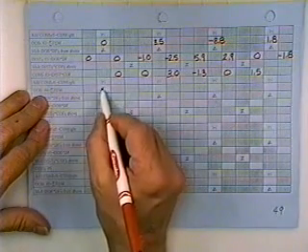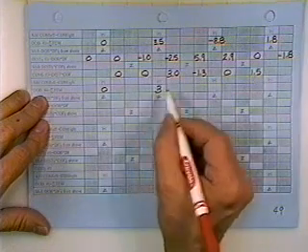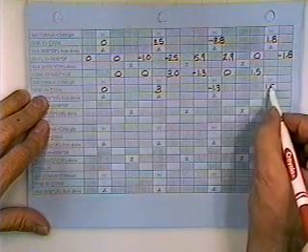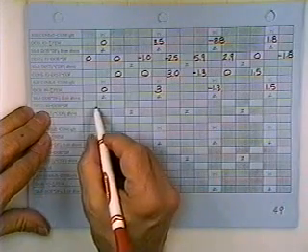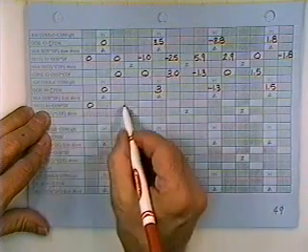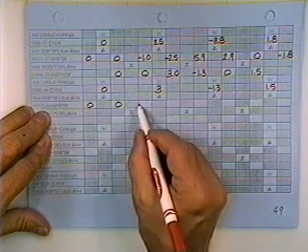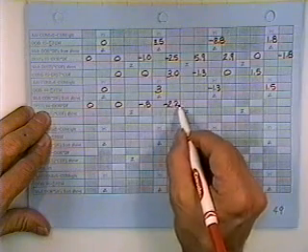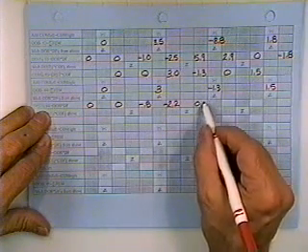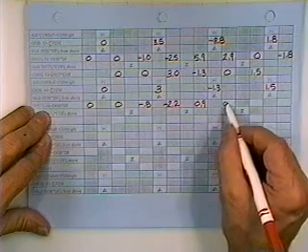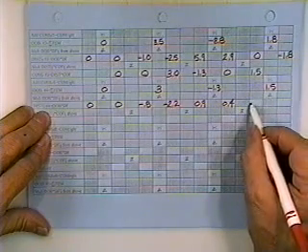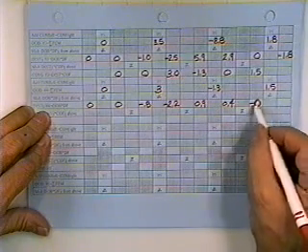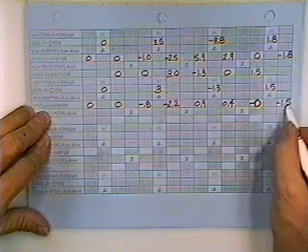Give them to me. Out of balance: 0, 3, minus 1.3, and 1.5. All right, read me the distribution for number 4. 0, 0, minus 0.8, minus 2.2, 0.9, 0.4, minus 1.5. That's a 0 there. Okay, I agree, because none comes this way and minus 1.5 goes into the wall.